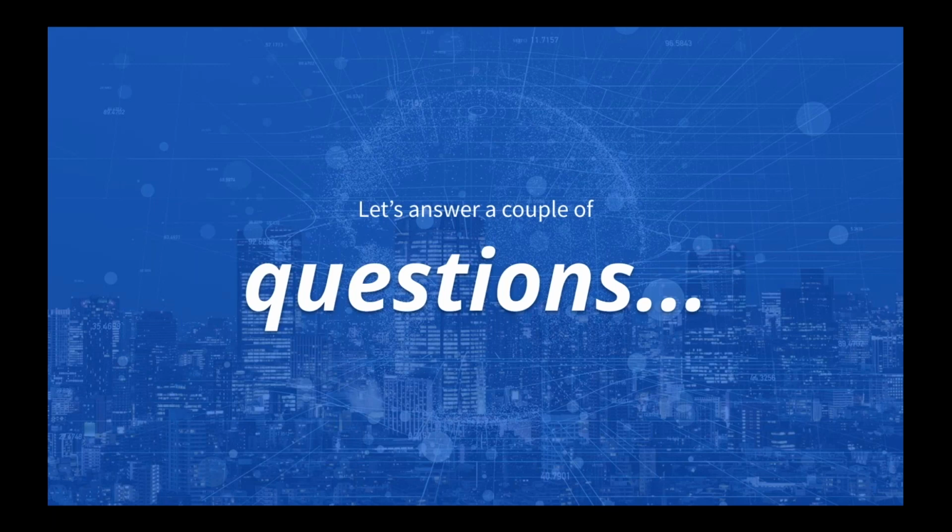While we're on the topic of coordinate systems, Dave, maybe you can say a few words about how we georeference IFC, because we don't have quite full coordinate system support there, but you can set some of the IFC parameters that help you georeference, correct? Yeah, IFC is georeferenced the way some of our other systems like SketchUp are, and a little bit like we have for Revit, in that IFC is assumed to be aligned to true north, and most IFC exporters will adjust to true north.